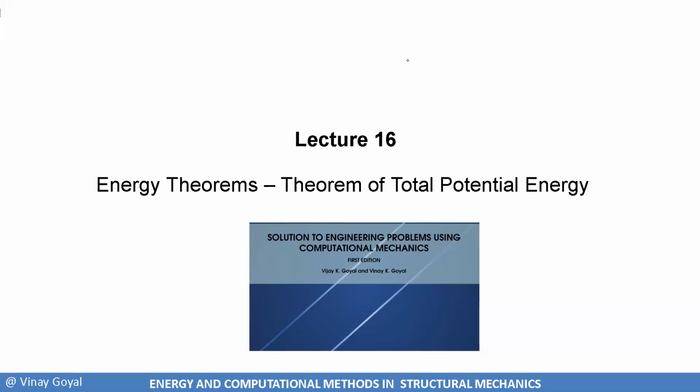That domain can be any domain, like an aircraft, a Navy ship, whatever it is, and we have to solve these equations. You cannot solve these equations by hand. I chose the structural concepts because that has the most equations. But I could apply it to fluid mechanics, where pressure and velocity field of the flow is important. You can see here I only have two variables. I could apply it to heat transfer, where I could have temperature as an unknown, and the heat flux are the loads applied. Again, temperature, just one variable. But what is nice about studying structural mechanics is I get 15 unknown variables.